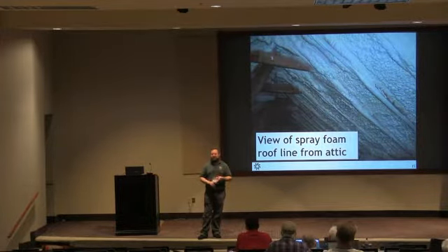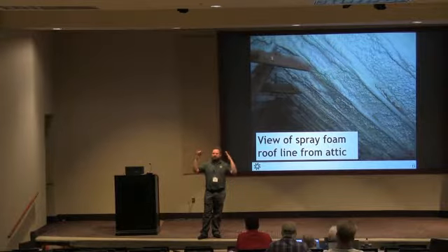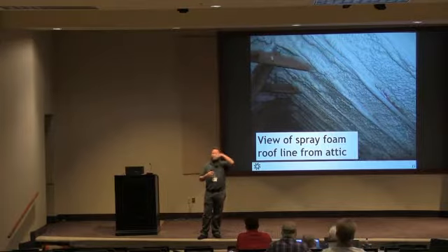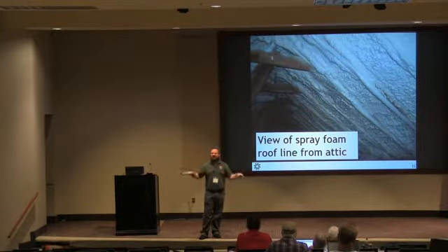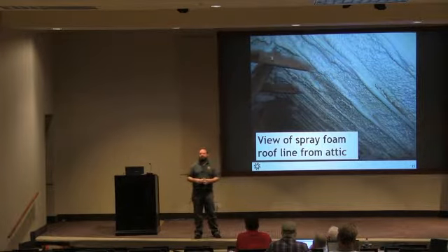One, it's not as effective in that location. You prefer to have it where it's keeping the backside of the roof deck from radiating all the way through, and where you're venting behind it, so you're expelling that air out of the house. The other thing is, if it sits up there like that, eventually it's going to get dust all over it. This sounds crazy, but if it's no longer shiny, then it loses its effectiveness as a radiant barrier. So when they lay it flat, it gets dusty over time, and that degrades its performance. So I would go through the trouble of stapling it up, basically.